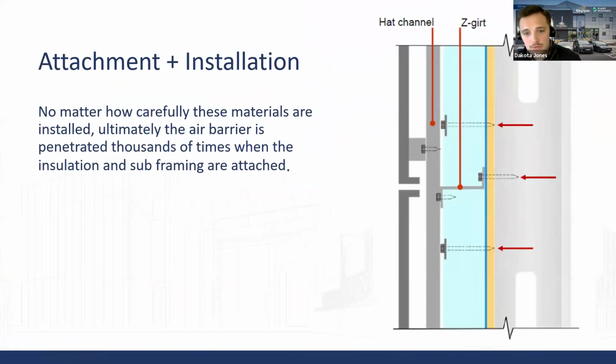But let's say everything goes well. We make our selections, we know what we're doing. Hopefully, we've gone above and beyond on our required minimum R values for our insulation. How do we connect this thing, right? Well, that's when we start figuring out our diagrams. And this is where thermal bridging gets to come into the conversation, specifically with Z-girts, right?